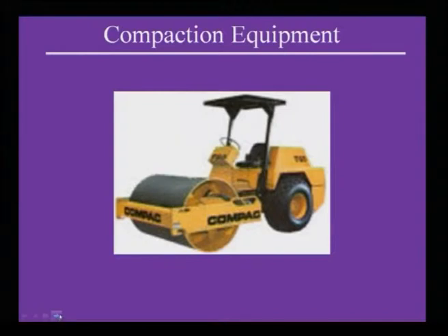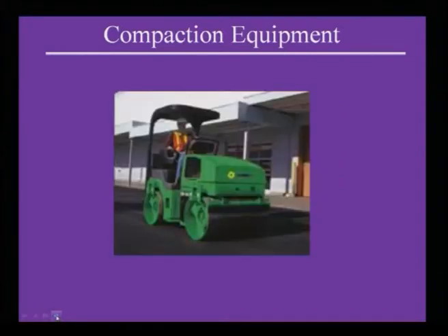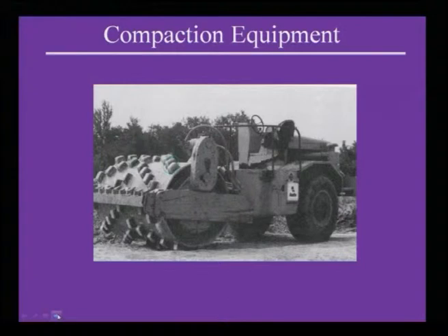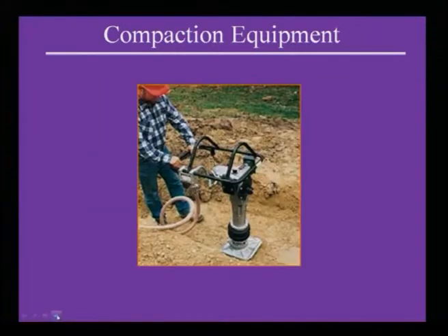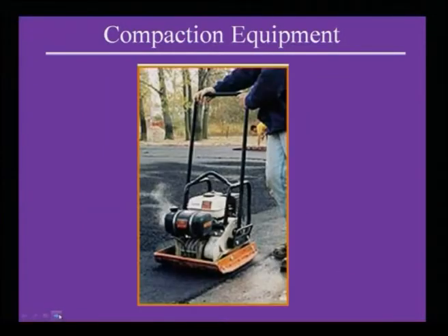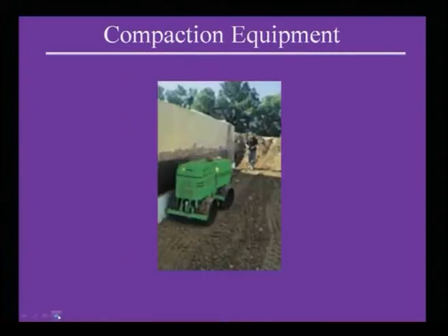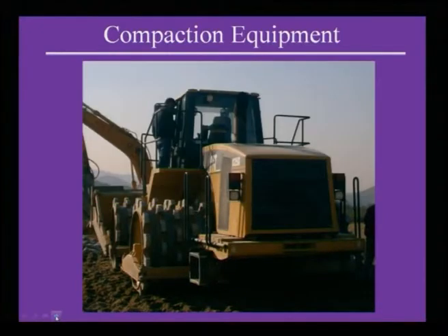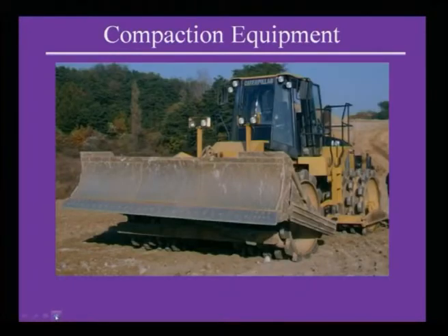Smooth drum, another smooth drum, sheep foot, vibratory, again vibratory, small vibratory. Look at this, how compaction is done by sheep foot. This will penetrate inside the ground. You look here, it penetrates inside the ground for better compaction.